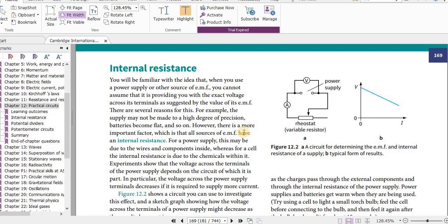You can observe that if you connect a multimeter, with the settings in the voltmeter settings, across a new cell that you just got, it will read maybe 1.5 or 1.6. After using it for a certain time, now you may be using these small batteries in clocks and other electronic devices, you can take one out when it has died and then check the potential difference across it. You will see that it will give a smaller reading.